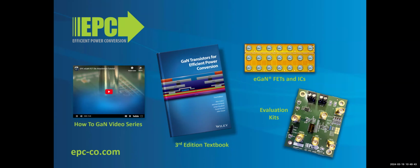The other type of approach I'm seeing, at least being studied, not yet in a product, is going multi-level, because multi-level is simply dividing the voltage into several levels, making it by nature already quasi-sinusoidal, and also reducing the dV/dt input to the cables. In that case, the idea is going multi-level without using any filter.